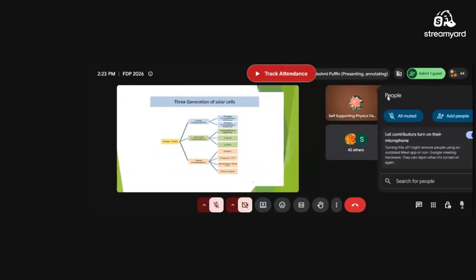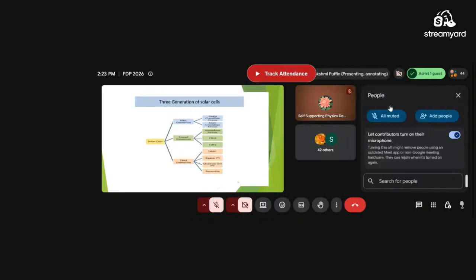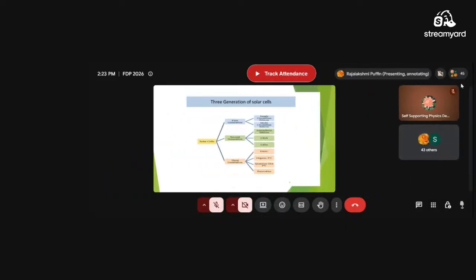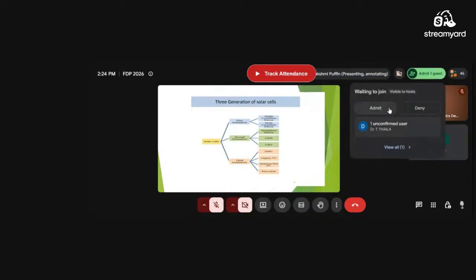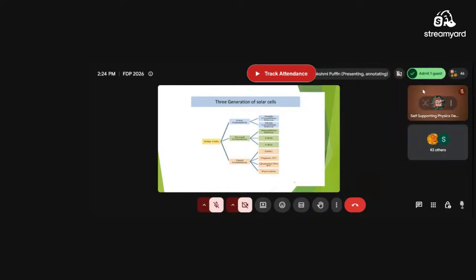Okay, so how does the silicon ingot get ready? We have to collect natural sand and put it through a technique like the Czochralski technique, and heat it to around 1800 degrees Celsius. Once heated, it gets molded, and we take the ingot as silicon crystals without any defect. So think about how much energy and how many natural resources we have to use for that.